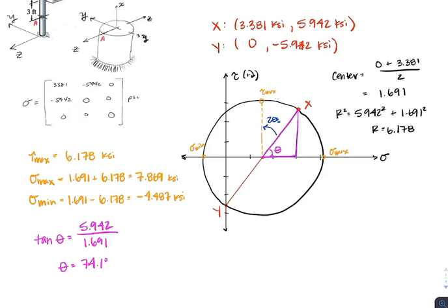And then the other angle we need to find is if that same line was rotated, but instead rotated down all the way to be completely horizontal. So we'll call that 2 theta p. So we'll start off with the easy one. We can obviously see that 2 theta p is just going to be identically equal to what theta is. So this is going to get us a theta p value that is equal to 37.1 degrees going in the clockwise direction.